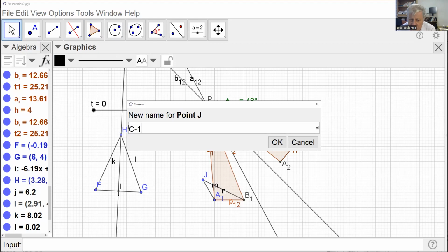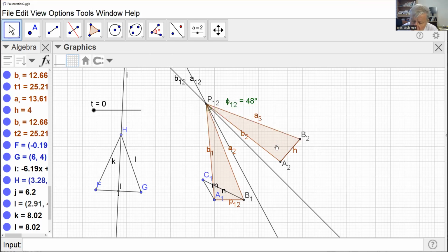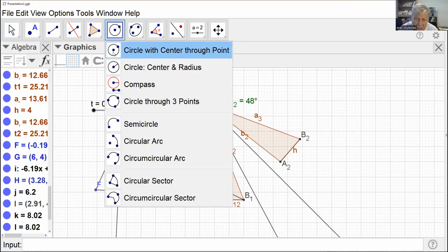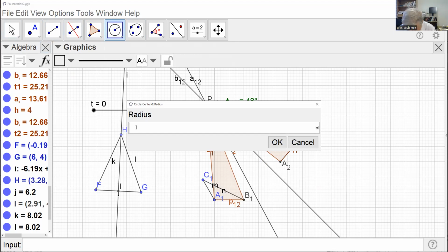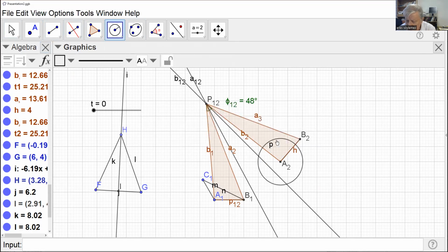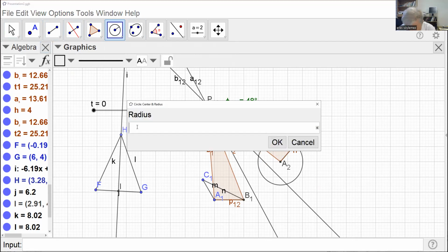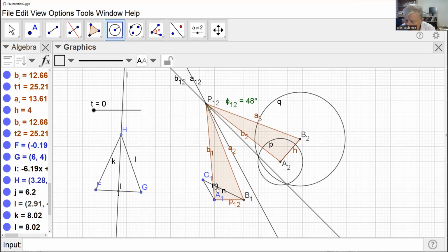It is the location of a point C in the first position, a point on the moving body. To determine C2, I can draw a circle from A2 of radius M, because this A1C1 distance is M. Since it is a rigid body, it has to be equal to M. And then from B2, draw a circle with radius N.